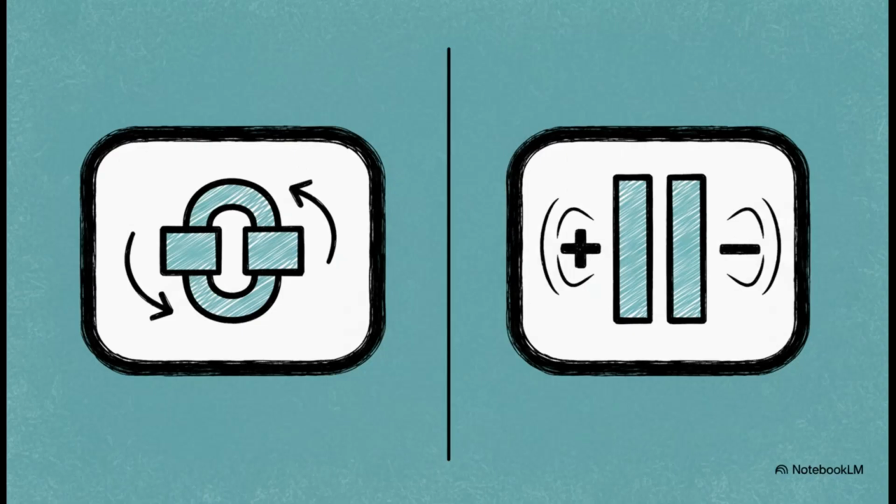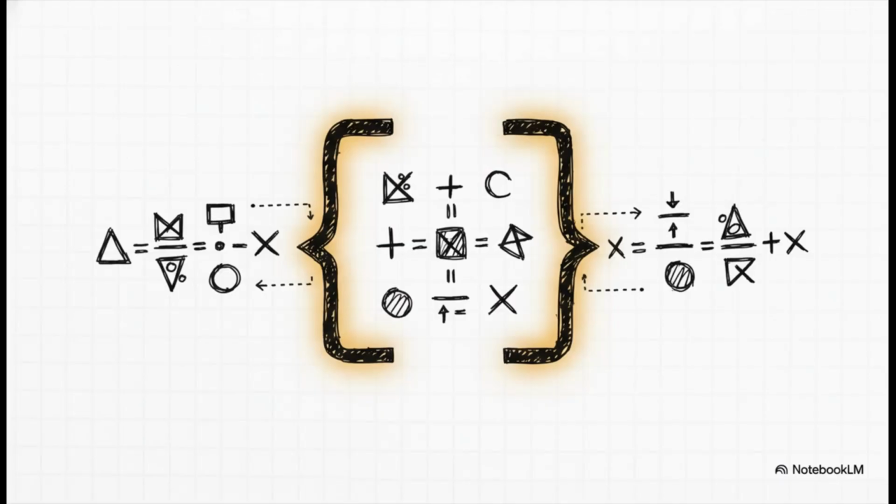And after we shuffle things around, we get these 2 beautifully clean equations. Each one tells us the rate of change for one of our key variables, our inductor current and our capacitor voltage, based on nothing more than the system's current state and any power we're feeding into it. Okay, and here's the final piece of the puzzle. We take those 2 separate equations and we bundle them together into one single, powerful matrix. This is what's going to unlock all the incredible analysis and visualization that's coming up.